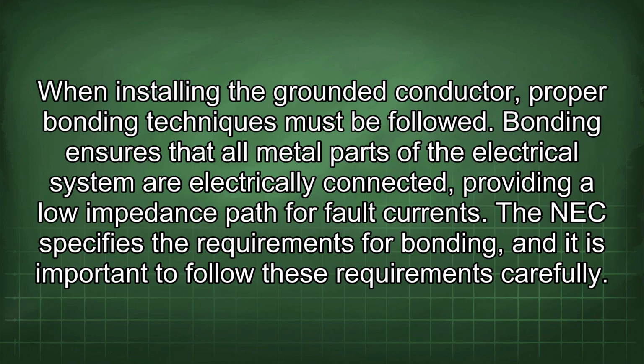When installing the grounded conductor, proper bonding techniques must be followed. Bonding ensures that all metal parts of the electrical system are electrically connected, providing a low impedance path for fault currents. The NEC specifies the requirements for bonding, and it is important to follow these requirements carefully.